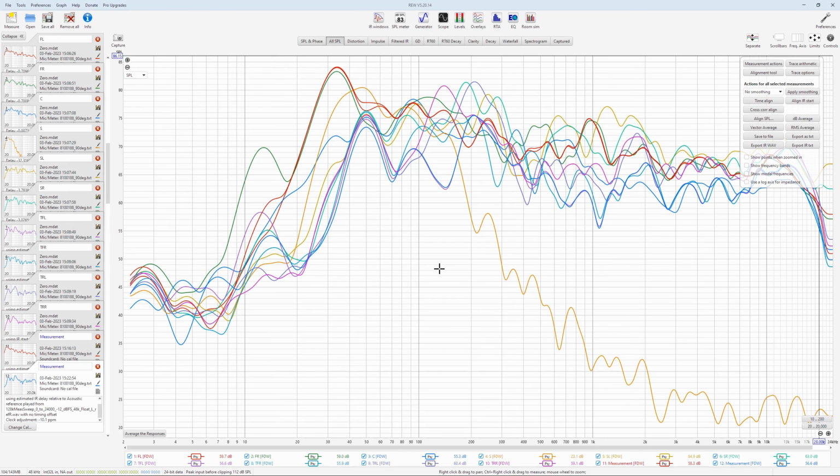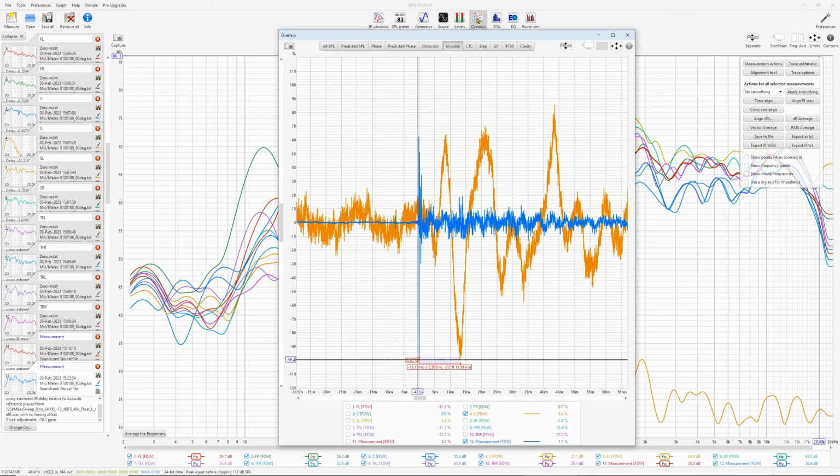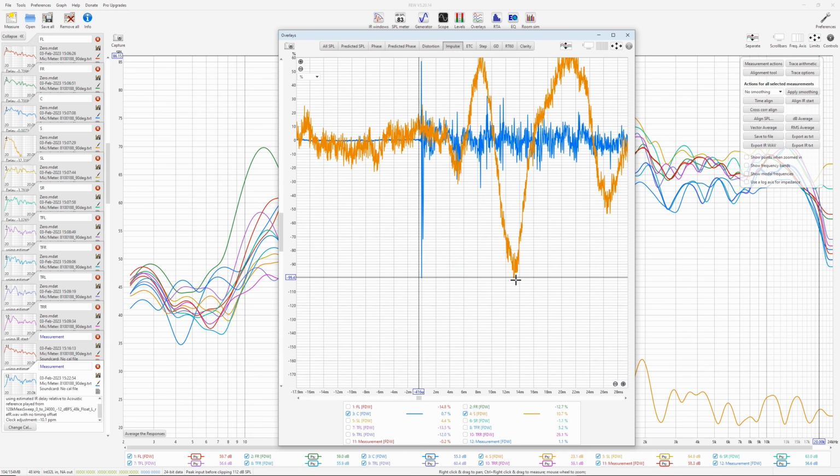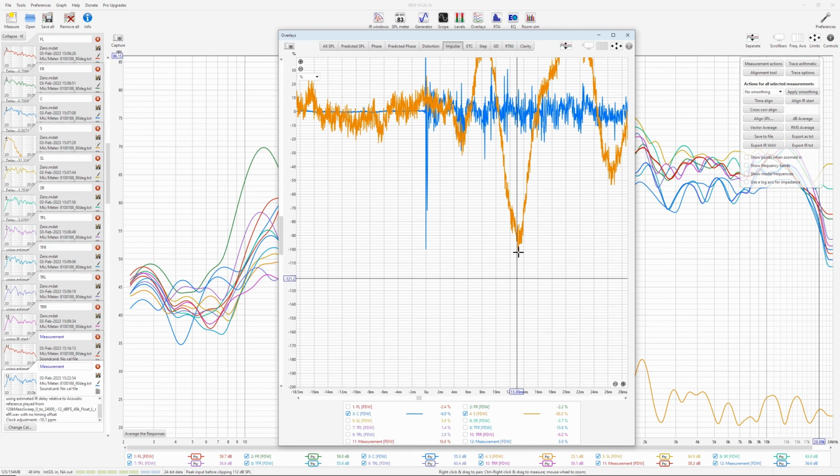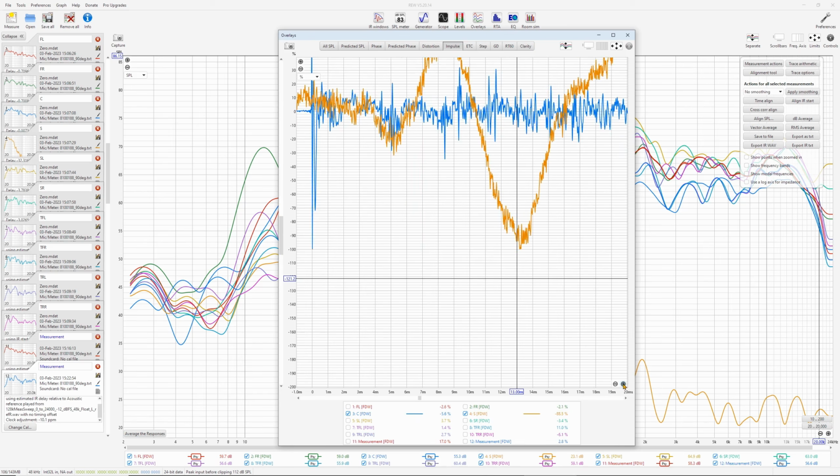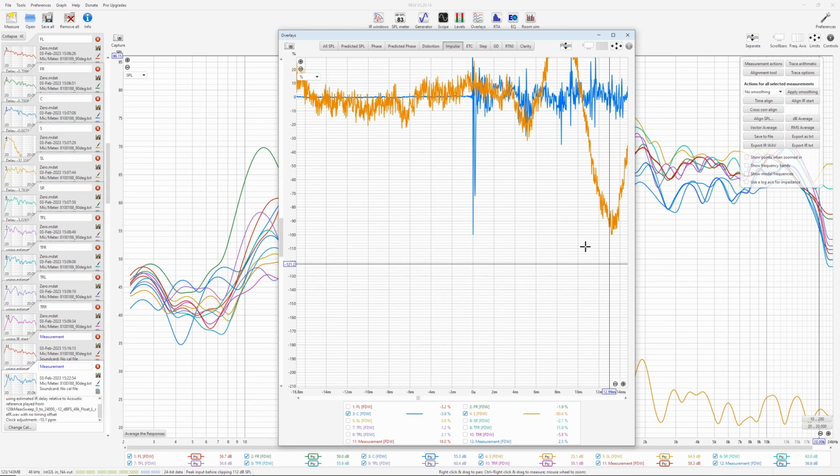Let's finally do subwoofer, because it might be sometimes harder to find. Then you can do the rest, I believe. So overlay, subwoofer, and center. Subwoofer impulse peak to the center speaker's impulse peak, and because of this line here you can't read the number, so I redo it. It's not accurate enough. Because if you get it accurate enough here, then you don't have to remeasure and realign and remeasure.